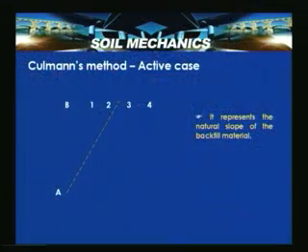With that, by drawing a number of trial failure lines passing through the heel of the wall, we will be able to proceed. In case you have uneven surfaces, or a berm which needs to be considered in the analysis for calculating the active thrust, this is possible. This graphical method is very robust in adopting and calculating earth pressures. So, let us look into this procedure, and we will look into problems on how the external loads can be calculated, and how we can do this in the case of active and in the case of passive.